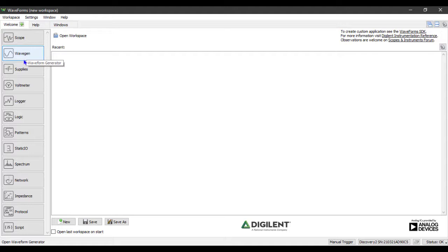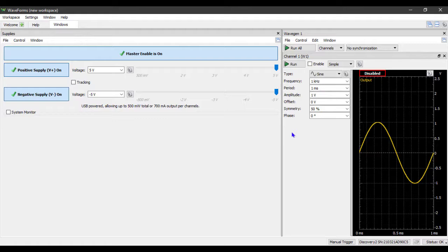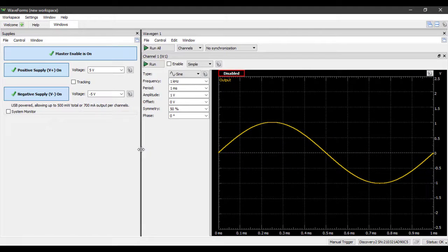Now we're going to specify the input from the waveform generator. Click on WaveGen. For this part of the lab, we're going to use a single sinusoid at various frequencies and 1 volt peak to peak. The first frequency measurement that you'll be performing is a frequency of 100 Hertz. So change the frequency in the WaveGen to 100 Hertz.